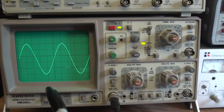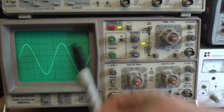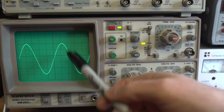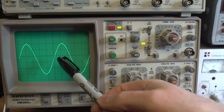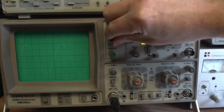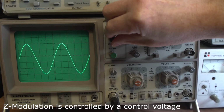So what's Z modulation? Well, you've got X and you've got Y. So what on earth is Z? It can't come out the front of the screen. We haven't got 3D or anything. So what's Z? Well, all Z is the intensity of the dot, the intensity of the beam. I can simulate it by turning the brightness down. That's Z modulation right there. So you can turn it down and you can make it brighter again.